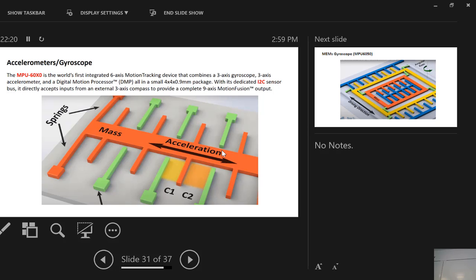That's very interesting. So if you can fabricate all these wires on the surface of the wafer, then whenever it's being shaken or vibrated, these will move around and change the capacitance, because they're nano traces. They can measure that capacitance and convert it into acceleration. So these are all inside that little integrated circuit.